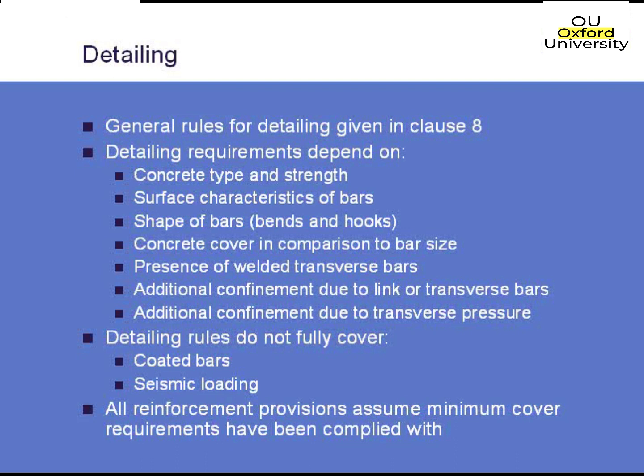Generally speaking, the detailing rules that are given in Eurocode 2 do assume that the minimum cover requirements have been complied with. And that's particularly important for anchorages and lap lengths, where the strength could potentially be reduced if you aren't complying with the cover requirements. So do keep that in mind. You do have to make sure that you are complying with cover requirements, otherwise you're not complying with the detailing rules in here.